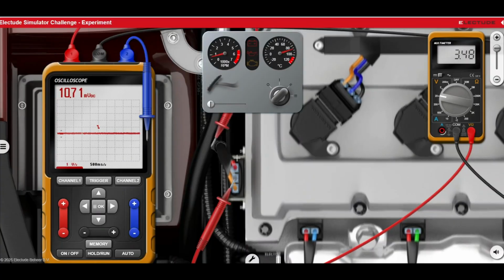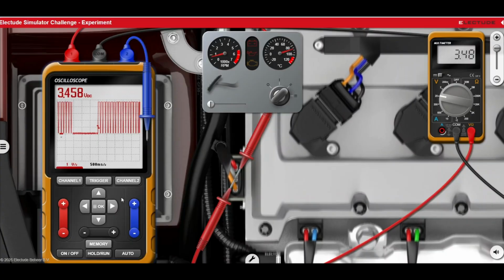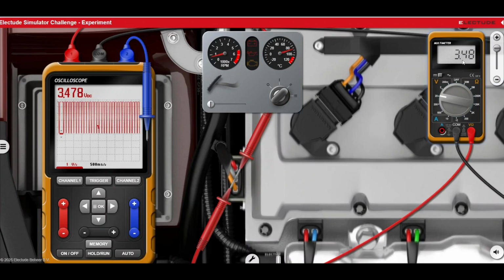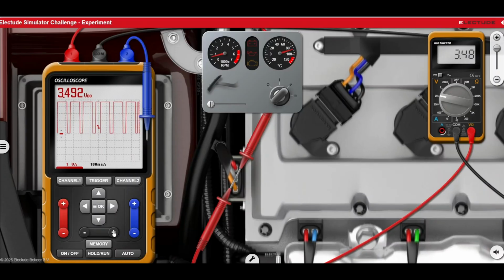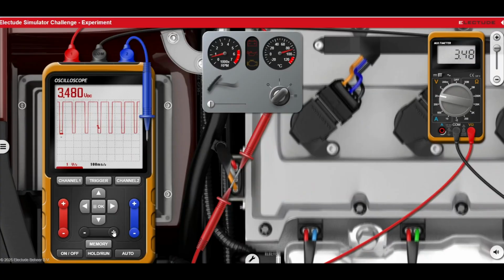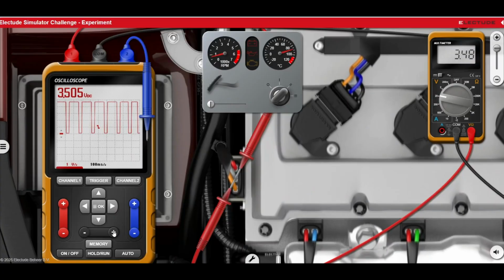So you are going to see that on the oscilloscope. You see this is a digital signal, but the multimeter is averaging that signal and giving you a continuous reading. But the oscilloscope is able to give you more detail about that signal. You see that? That shows you the importance of an oscilloscope. There are times when only a multimeter is sufficient. How do you know? Look at the wiring schematic.